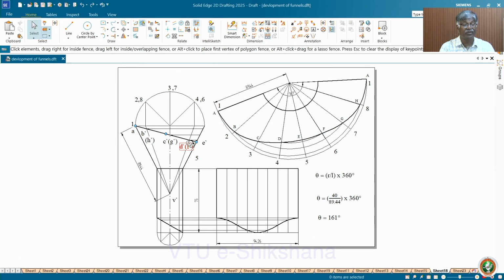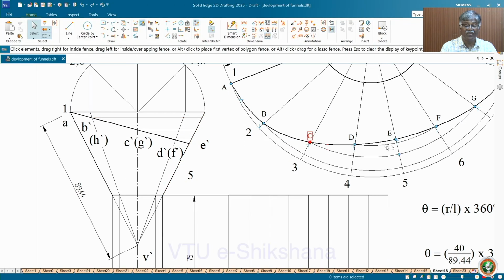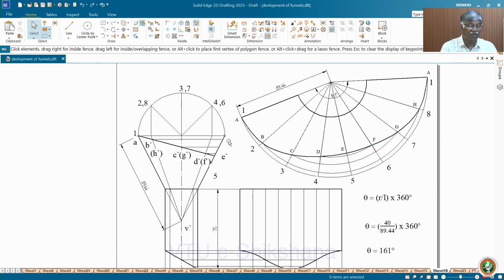So I'm going to take a little more in the actual model and also for explanation. Here, this is the inclination. It is very small, so that's why you got a very steep and also very smooth curve here. Now here, this is the truncated cylinder. This is the profile. This is very familiar to you now. The procedure is very easy. This is also easier. When you take true length, then you will get the correct answer. If you take direct length, then it's wrong. So definitely for all cylinders and cones with truncation, you must be very careful. You must take true length and do it.